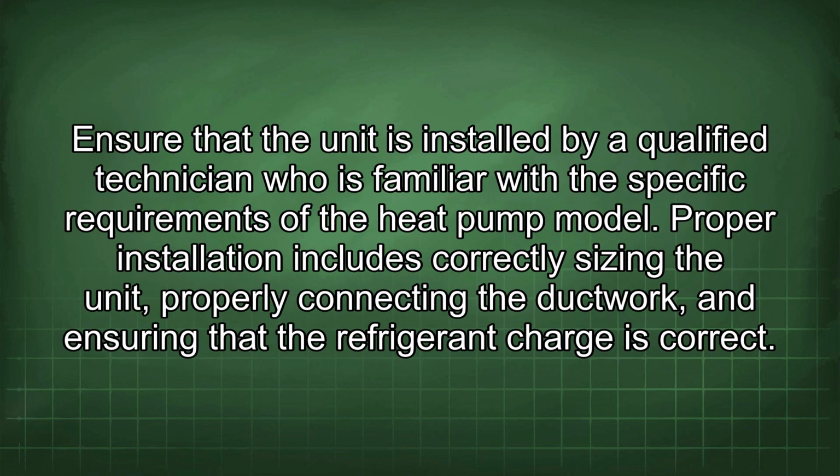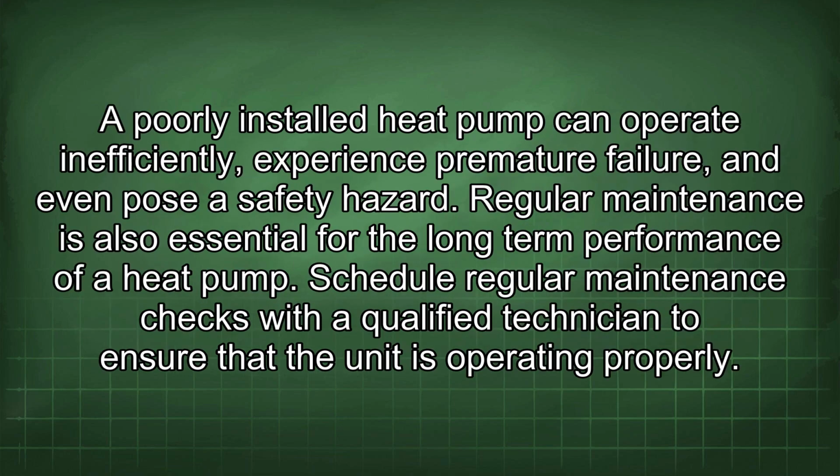Ensure that the unit is installed by a qualified technician who is familiar with the specific requirements of the heat pump model. Proper installation includes correctly sizing the unit, properly connecting the ductwork, and ensuring that the refrigerant charge is correct. A poorly installed heat pump can operate inefficiently, experience premature failure, and even pose a safety hazard.